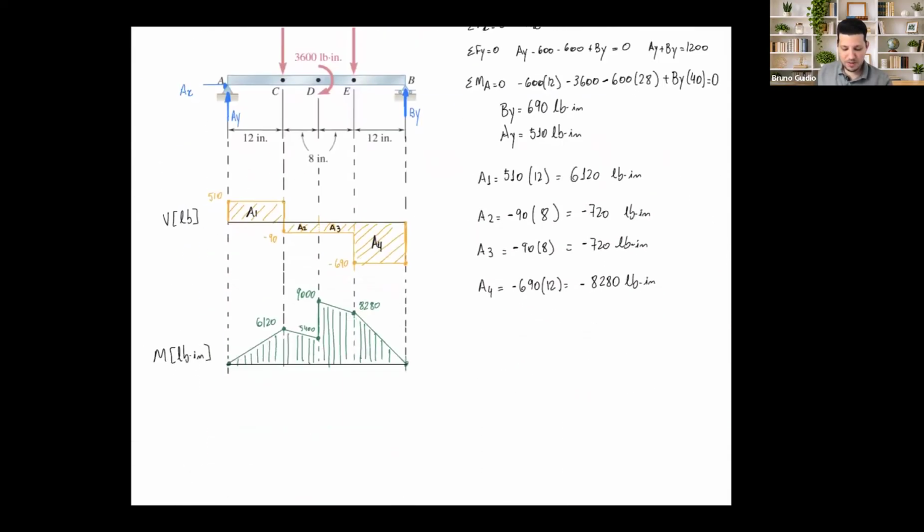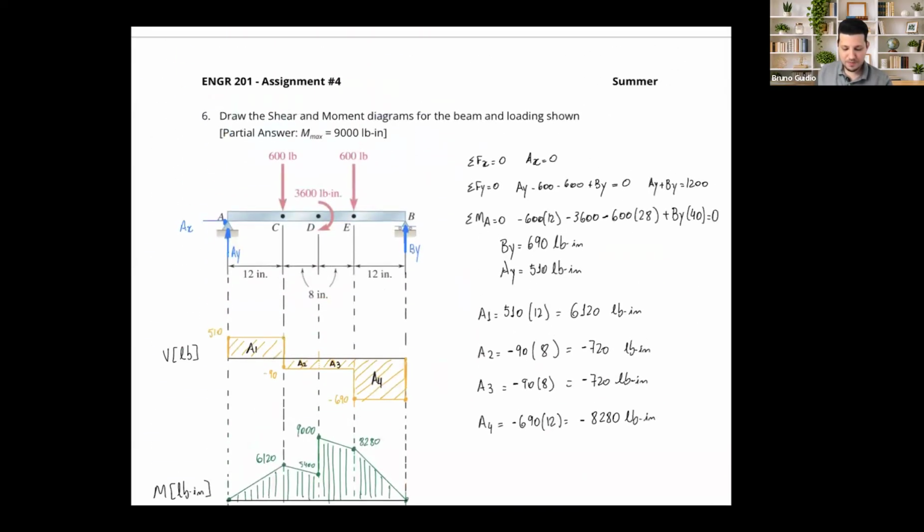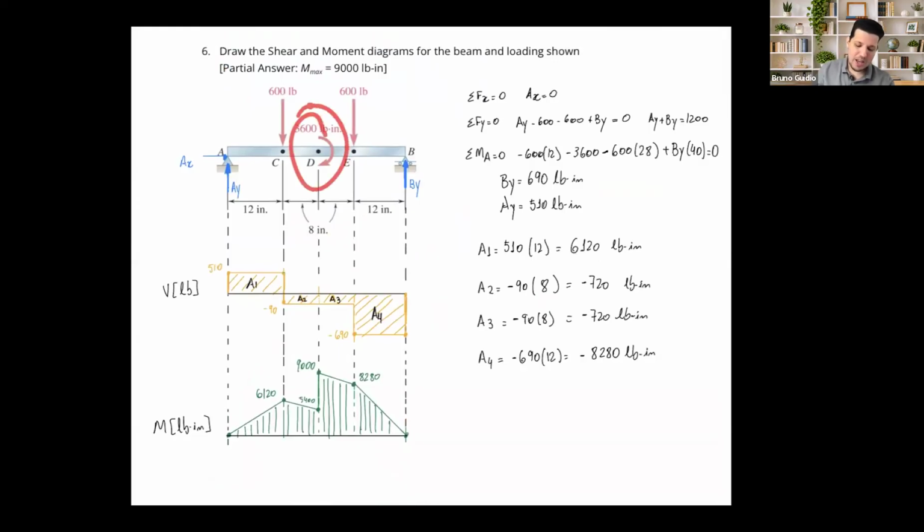And my last problem, yes, my last problem here, okay? My concentrated moment is in the middle, just for you to visualize what's going to happen. In the shear diagram, nothing's going to happen in the middle, it's just going to keep straight. And then right here, we have that. And once again, for the equilibrium equation it is a negative moment because it's clockwise. However, for the moment diagram, this is going to be a positive moment. Why? Let me get my...